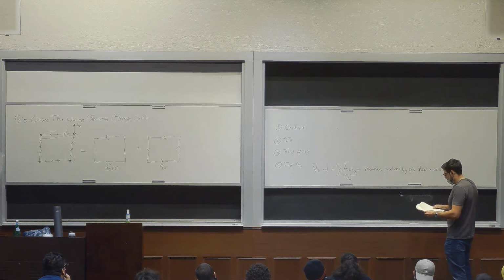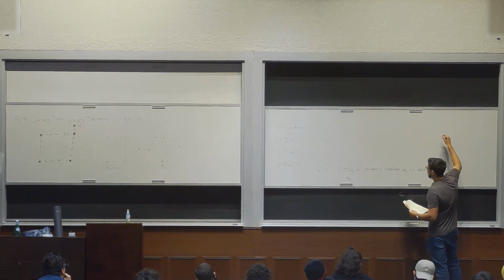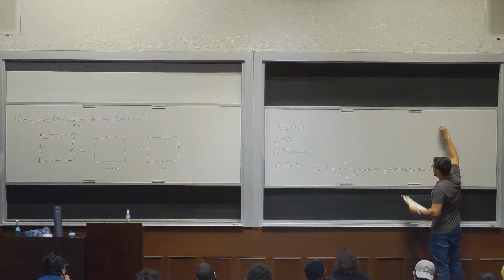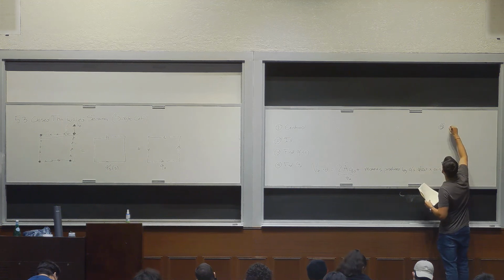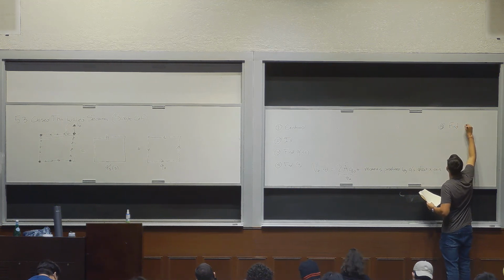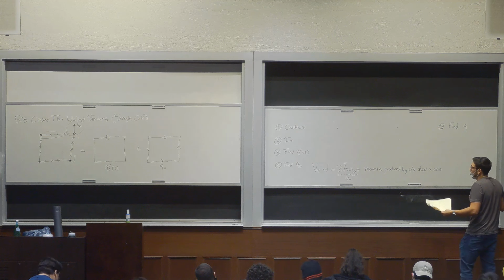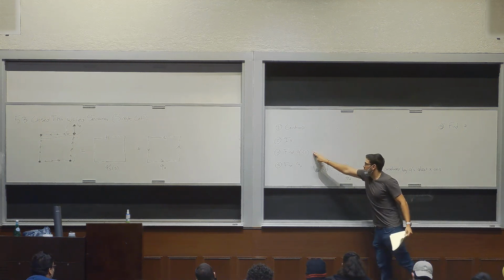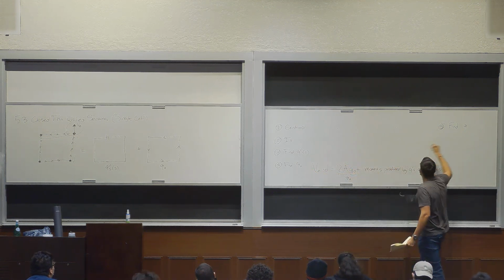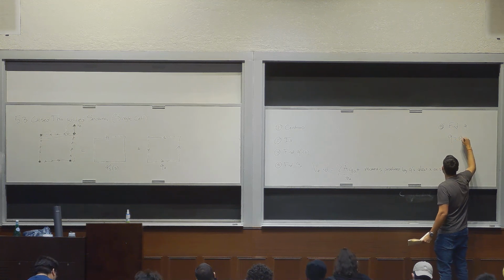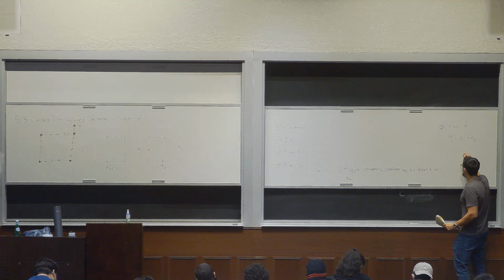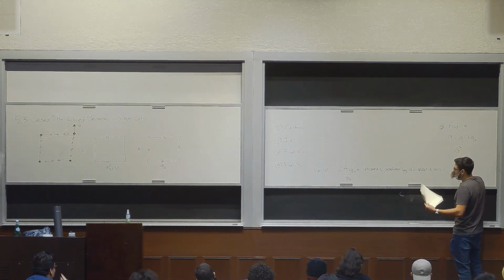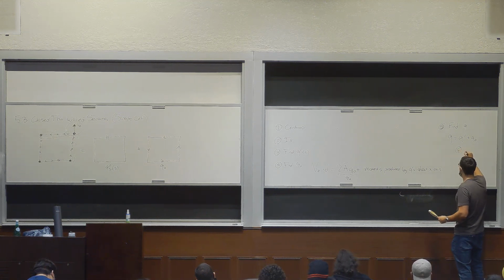And then step 5, I guess. This won't make much sense until I do the example, but it'll make sense. Step 5 is to find Q, the real Q. At this point, we found Q prime and we found Q naught, so all you've got to do is add them. So Q equals Q prime plus Q naught. Simple as that. And step 6, which might be an optional thing for the problems, is to find the shear center.